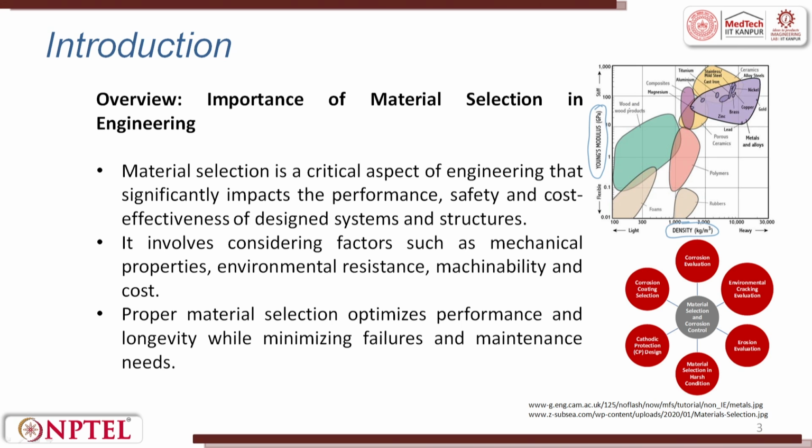If you look at it, he has placed here wood and wood products. Here he has placed composites. At some place density very high, he has placed metals, you can see here. So, these are sometimes cast iron products, titanium falls here, magnesium falls here. So, if you see here, magnesium is lighter or the density is lesser than titanium. In that case, magnesium should be popularly used for various moving parts, which is coming into existence. For example, aeroplane, automobile. Now, we are trying to look at magnesium.